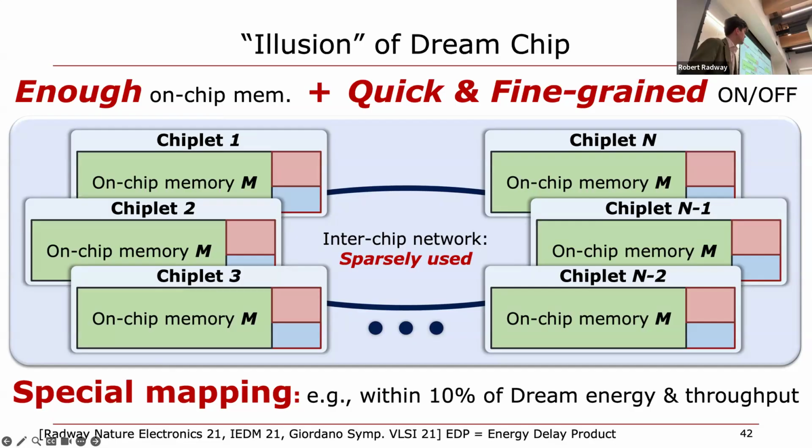You can just explain again. Yes, sorry. When I say chiplet, I just mean a chip, a custom IC. There is a technique called 2.5D integration, which is basically taking multiple of those dies and putting them in the same package on what's called an interposer. The idea is that with today's GPUs, ideally we would want them to be larger than what's called the reticle limit, the max size that we can fabricate traditionally. So you need to separate that into smaller chiplets, smaller chips, and connect them very tightly to have the same performance or energy efficiency as that ideal larger chip.